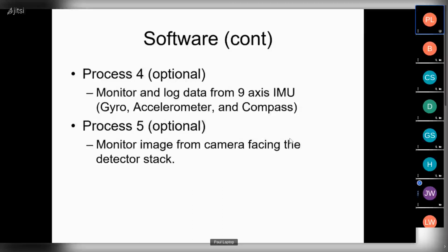Paul, this is John W. That's my concern, this visible red laser shining across 100 feet in the sunlight at phototransistors. Have you looked at modulating them, like an IR remote control, with a narrow band, maybe using IR, and then recovering the signal strength with AM demodulation, a phase synchronous demodulation? Yes, I have not looked at that. I've thought about that, and I hope that I don't have to do that.